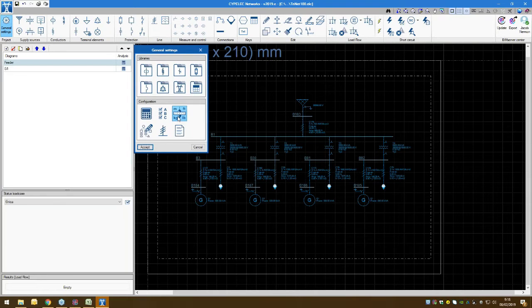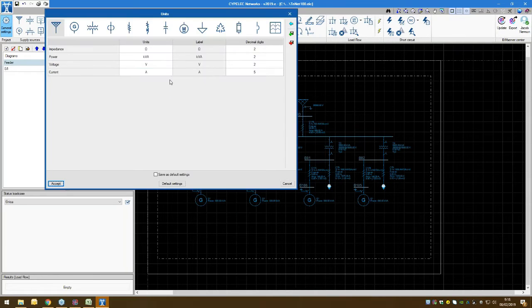Next is the units tools. And so this is used to alter the individual units associated with different elements and different properties. It's pretty simple to change the units. You just simply click and it will open a drop-down menu. You can adjust the decimal digits as well. And you also have the option in the top right corner to import a predefined unit system, which will apply universally.